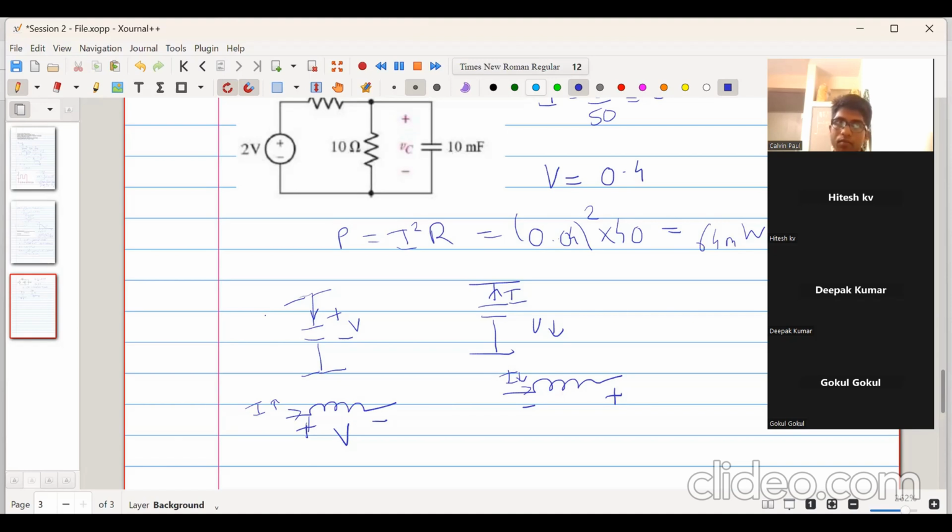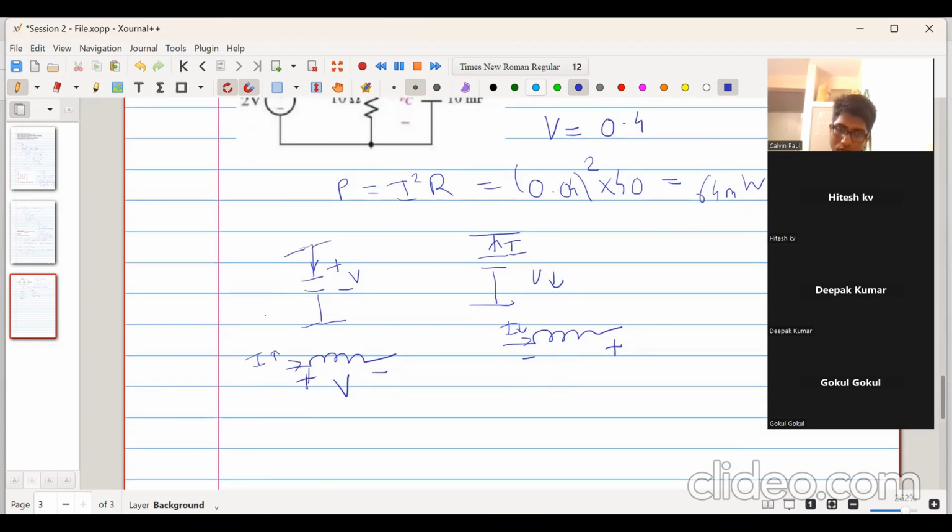So see, actually over here, the direction will be the same in an inductor, just the polarity will change. In this case, the inductor current is at some particular value and it will be rising. Rising means the inductor is getting more energy, it is getting energized.